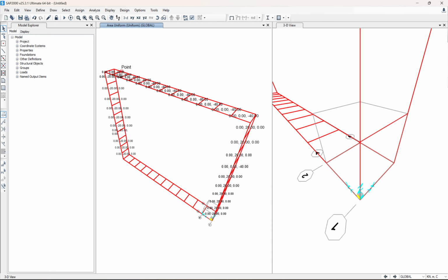Likewise, if there are loads from the road, you can apply them as well. I'm not going to spend time on that over here because it's already in the previous video. Now all the things are done. At this point, whatever loads you have, soil pressure, the road above, the soil above, and maybe surcharge loads should have been applied, unless it's a load from an axle. So we can apply those axle loads later.